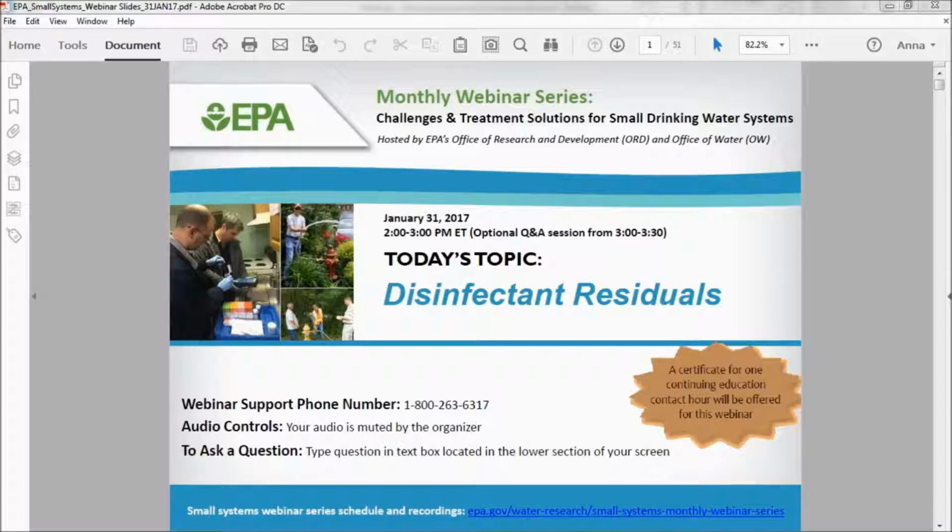Well, if we think about free chlorine, we generally think about hypochlorous acid being the effective disinfectant, and based on pH, as you increase pH, you're favoring the hypochlorite ion. So at pH 7.5-ish, you're about 50-50 hypochlorous acid and hypochlorite ion. I can't tie this to the higher detections at higher residual levels, but in general, as pH decreases, you're favoring the more effective disinfectant, hypochlorous acid, which you'll see in the CT tables has lower CT values because of that. At higher pH, you're favoring hypochlorite ion. So in essence, you're maintaining probably a less potent disinfectant, but you're still maintaining a disinfectant.